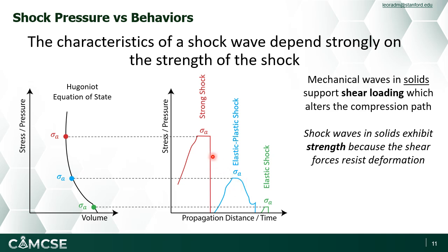At some point, though, we end up with a plastic wave that is not just slower, lagging behind the elastic wave, but actually overtakes that elastic wave. This is called the strong shock approximation, often an overdriven shock. And under these conditions, we really still see a single shock type of geometry, but now it's a single shock that is very much creating plasticity and damage in the material.